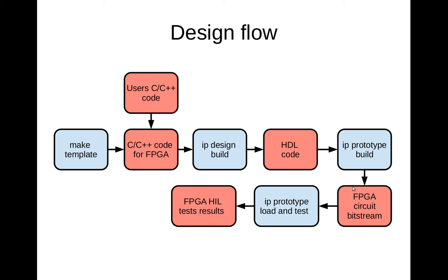At the moment, we are on this stage of the design flow. We have FPGA circuit bitstream that is supposed to be uploaded to the actual hardware, and it is the right time to check all the interfaces on our board, including USB, Ethernet, and it is also important to make sure that there is a power supply on our board.